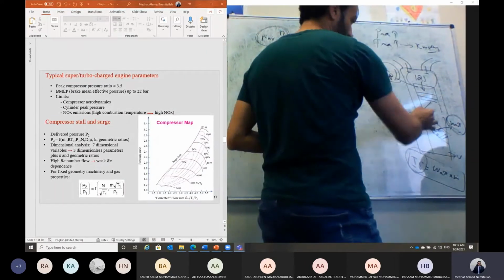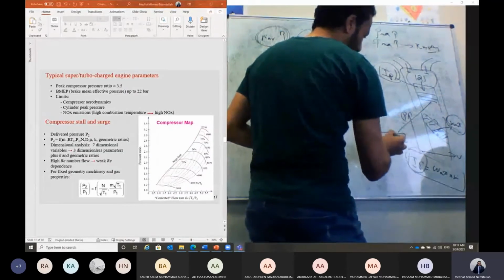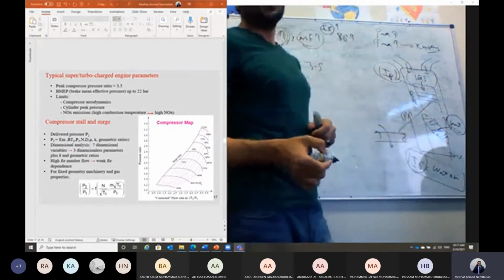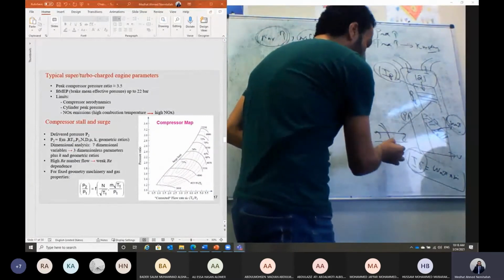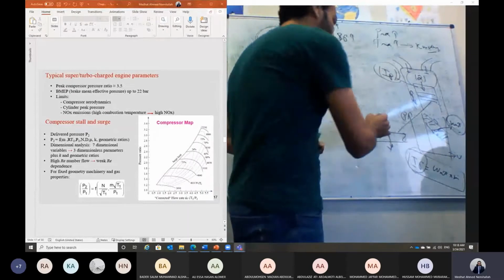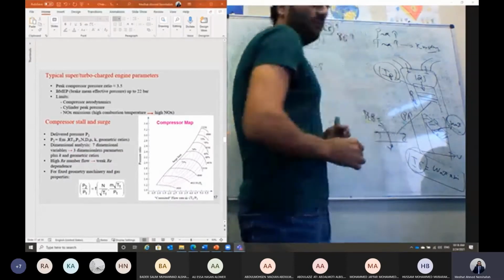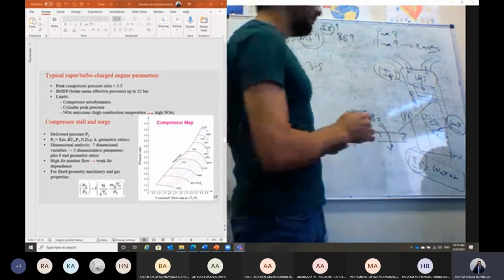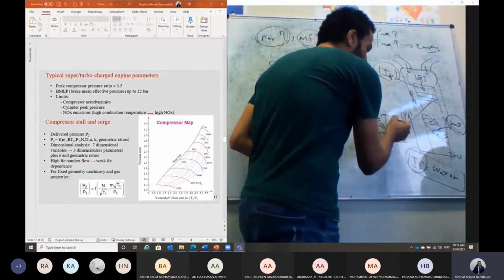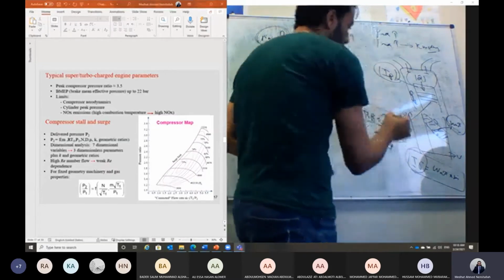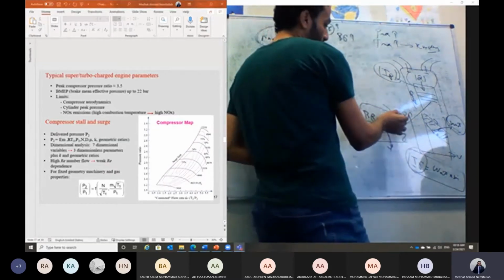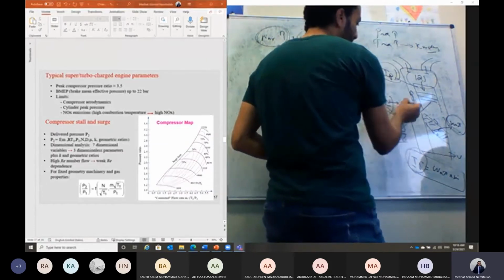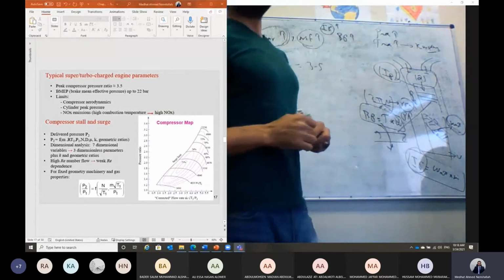This piston, guys, is connected to a crankshaft through a connecting rod. Then we can convert this reciprocating motion of the piston to angular motion on the crankshaft. The power on the crankshaft, which is shaft power, we call the brake power, and that should be the final outcome of the engine. Brake power is equal to the torque multiplied by omega, where omega here, not the work, is 2πN over 60, and N is the revolutions per minute in this case.